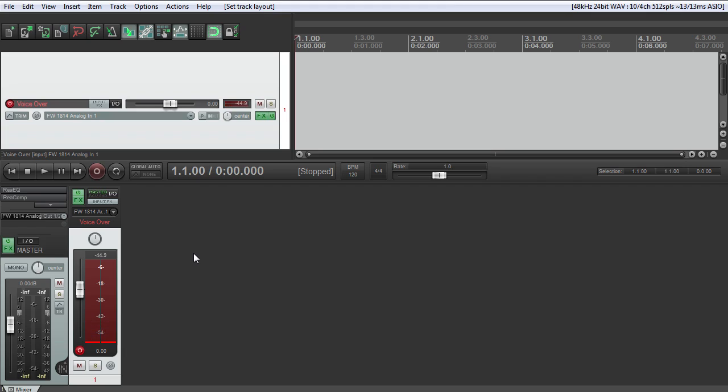When it comes to setting levels, you do not need to record a super hot signal and ride the gain knob. If you are just starting out, you might want to set the levels so that you are peaking at around -10 decibels on the meters of your recording software. Peaks are the loudest segments, and there is usually an indicator of the peak level, so you'll be able to easily see where you are at.